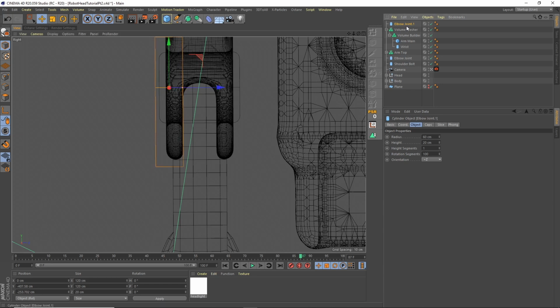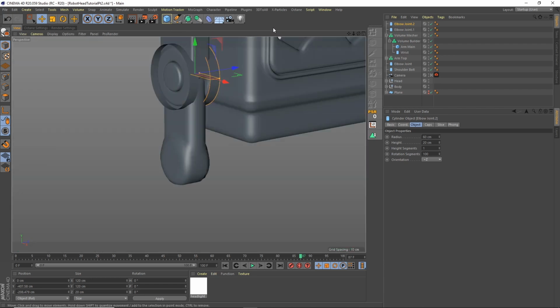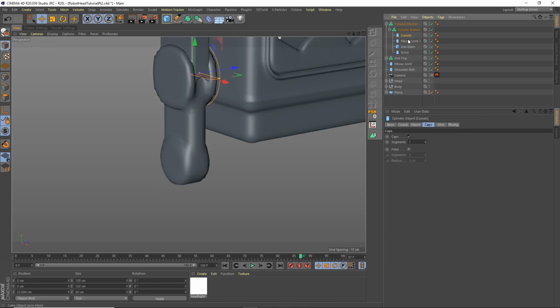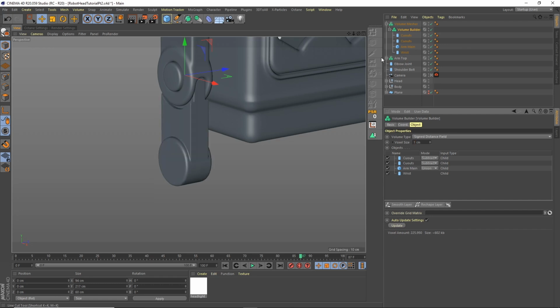So let's just copy that again, move it over this side. And let's have a look in our front section. Now I seem to have got caps turned off, so turn them back on. I don't want the fillet, that's what I don't want. Let's bring those both in, and we'll call these cutouts. And then let's subtract both of those. And let's turn our voxel size down to like 1 and add a smoothing on. That kind of brings it all together.